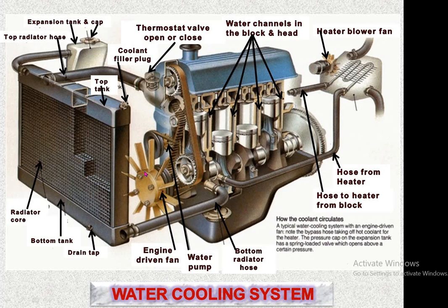So this fan runs and it sucks the air through the radiator core. Then the water pump, which we can say sucks the water from the radiator. Then the bottom radiator hose. This is the bottom radiator hose.